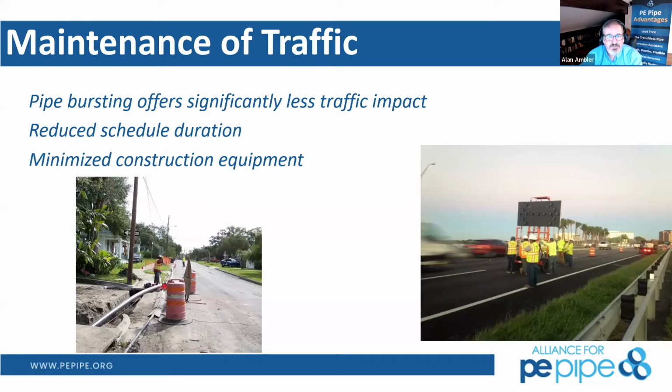But a big saving for this project is they replaced 1,800 linear feet of 8-inch cast iron in 3 weeks, when traditional open cut would have required temporary barrier walls, traffic shifts, and taken at least 6 months with lots of impact.